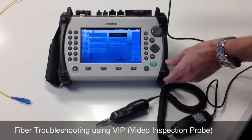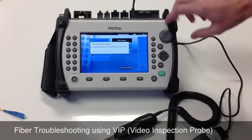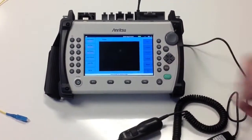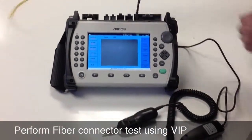Since the majority of fiber problems arise from dirty or damaged connectors, we are now going to walk through our video inspection probe test. Connect the VIP into the USB port and enter into the VIP application.